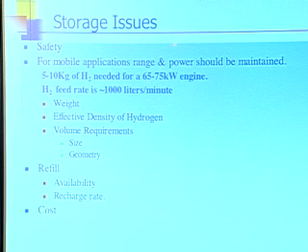So you need a certain amount of power, about 50 kilowatts, and maybe up to a 100 kilowatt engine. The small Toyota fleet that's running around California, a fuel cell SUV fleet, has 90 kilowatt fuel cell power plants in there, and they have performance that's comparable to a gasoline SUV.